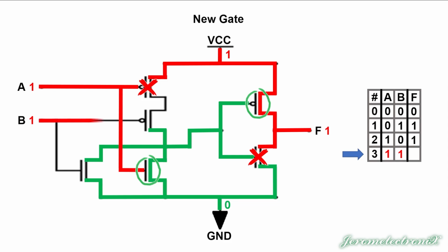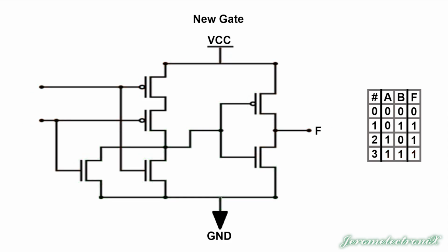B, that's a 1 that goes into the PMOS, which of course is blocked by 1s, and a 1 going into the NMOS, which of course allows flow, but that's not very exciting because it was already there. So now we can go over to the right side and look at what is going to happen to those gates. It looks like a 0 going into a PMOS. We know that's going to flow. We already have seen that it's flowed over to the F1. The 0 into the NMOS below there blocks the flow. So we have 1 here.